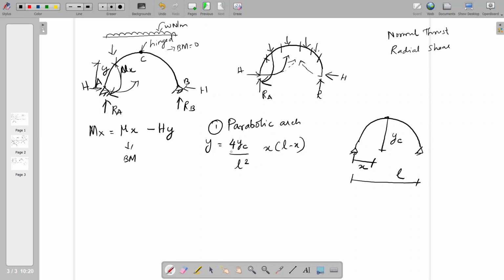So we can have some point here. At this point, the deflection is 0. There is no deflection because of the support condition. At x equal to L, y equal to 0. At the crown point, there is no slope. So, x equal to L by 2, dy by dx is equal to 0. We can prove the slope is 0 at the crown point from this equation.